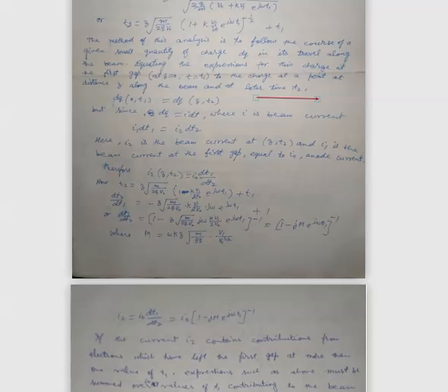So therefore at these two locations of the charge, we can write down the equation I1 dt1 equal to I2 dt2, where I2 is the current beam at Z at t2. Later we will consider it at the catcher cavity grids, and I1 is the beam current at the first gap, which is equal to I0, that is the DC or anode current. So therefore we will have the equation I1 dt1 equal to I2 dt2, from which the current I2 is given by I0 into dt1 over dt2.